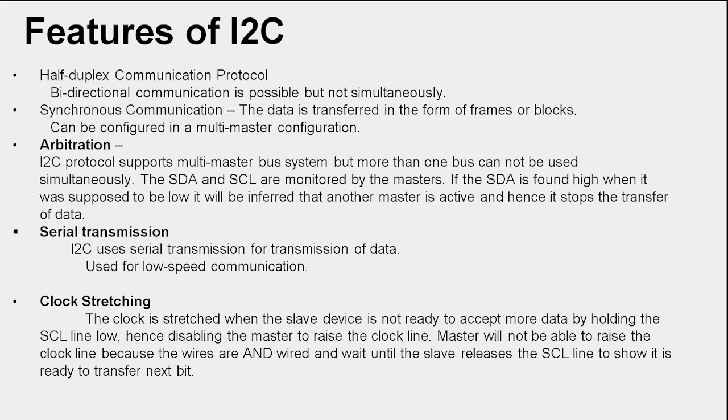Whenever the SDA line is found high, it means one of the masters is active, so the other master will stop the transfer of data.